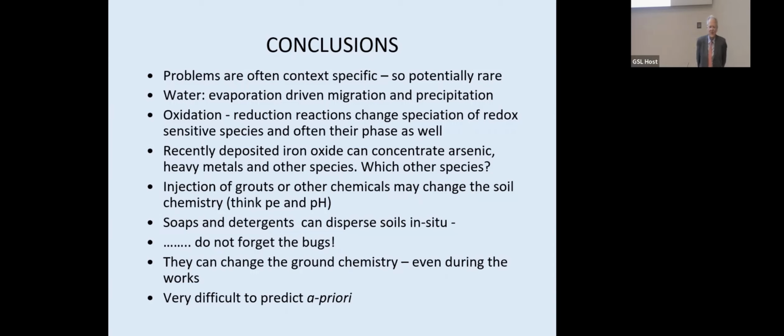I don't do corrosion, so I think the answer is yes, because you're always going to get corrosion when you've got two different metals in contact. I remember when we did Baker Street to Bond Street, where there's acid groundwater there. When we did Old Street, the answer was to line it with stainless steel, and then there were the questions about stainless, and apart from anything else, the unbelievable cost of the stainless. But we tried then to look at coatings for the segments to try and protect them from corrosion.